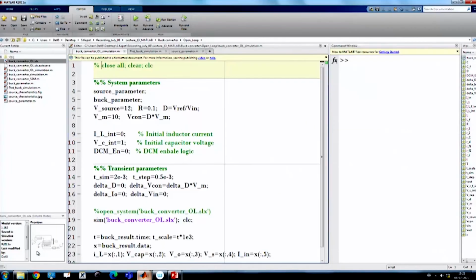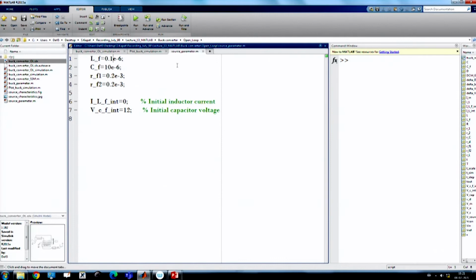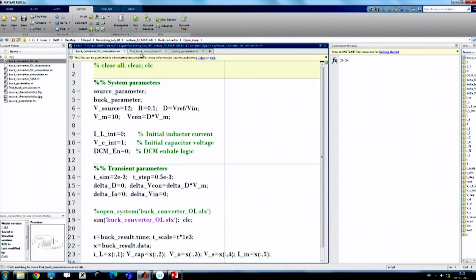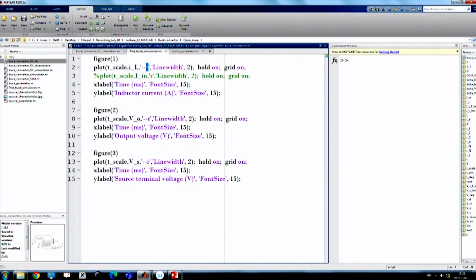Now, what will happen if the impedance of the source changes? Suppose you put a thicker wire, that means a long cable wire, where it introduces sufficiently large inductance, 1 microhenry, earlier it was 2.2 microhenry, and we want to repeat this simulation, and I want to create another color, green color, okay, and I want to see the effect.